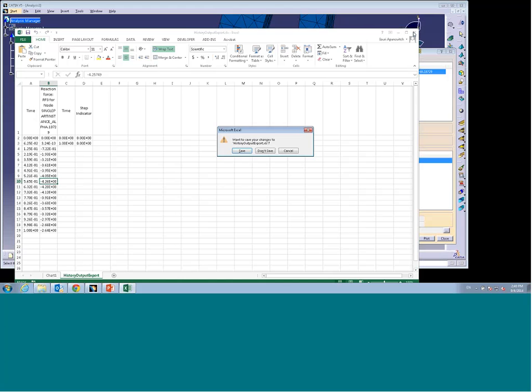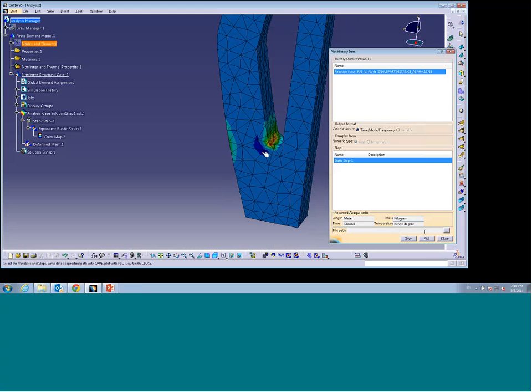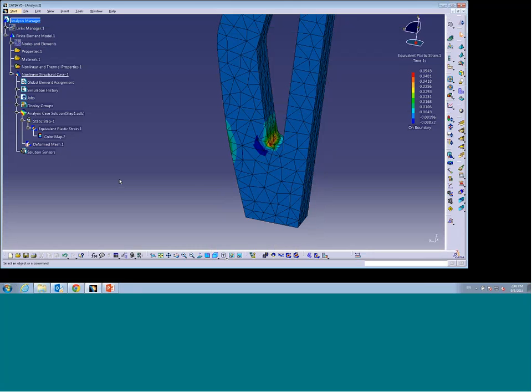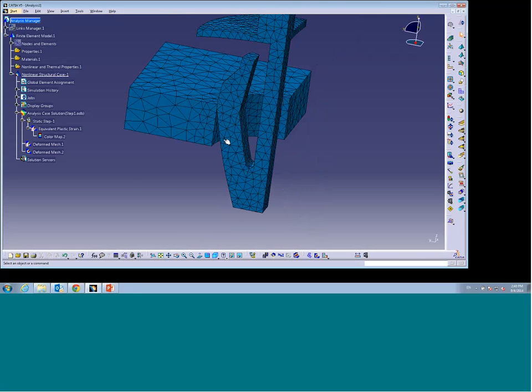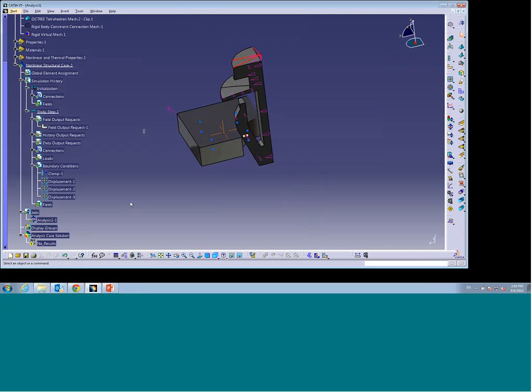As you see, we were able to successfully simulate the first step in the simulation, which was insertion of the clip up to that point. So let me pop up the plot again. Okay, so essentially we only simulated until the position in which the clip starts rubbing against the smooth surfaces. We want to add some other steps to actually make the full insertion of the clip. Okay, so I'm going to detach the base, and I need to create some other static steps. Okay, so I'm going to click.